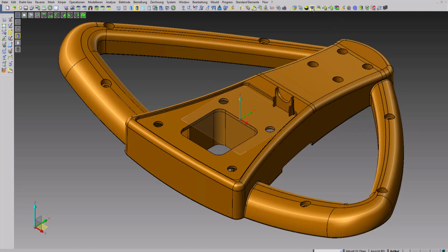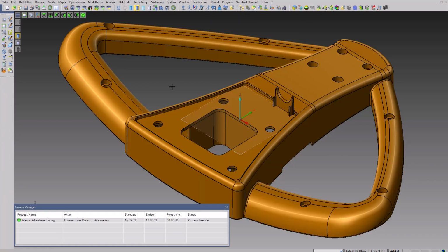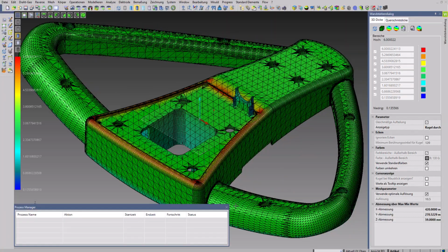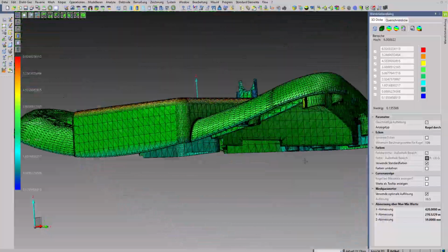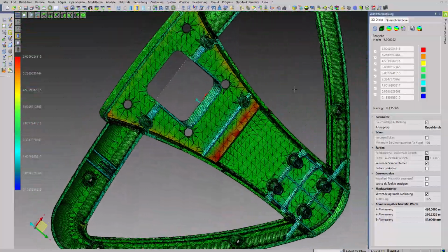Next, they concentrate on creating the two halves of the part, technically called the split line, which separates the core and cavity. For simplicity, they are the top and bottom of the part, while the gap in the middle is the void filled during the injection phase with required plastic material.